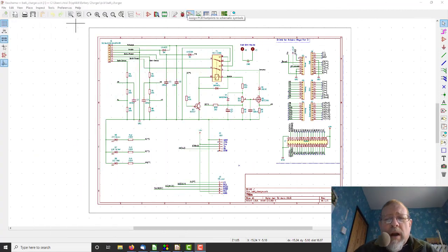Okay, so I've basically finished it now, and I did add a couple of capacitors, just 100 nanofarads, on the voltage sense lines, just to smooth them out, just in case. A couple of capacitors on the supplies in case any nasties get on the wires, and a couple of grounded pads to mount the heatsink to.